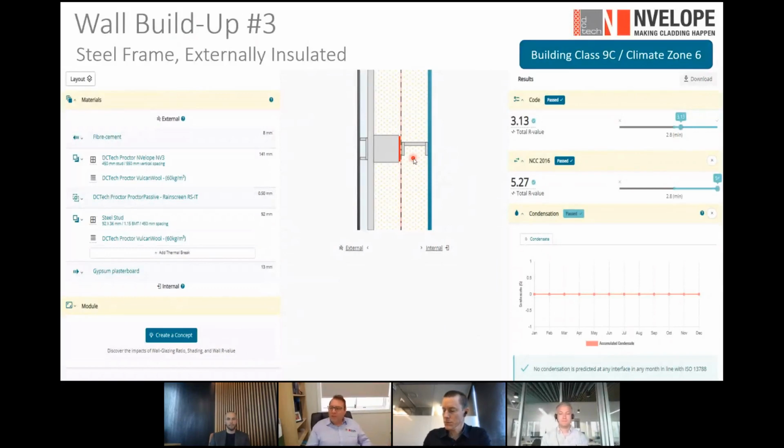But the big plus here is that we've moved the dew point. If you were internally insulating, your dew point would be expected behind the vapor permeable membrane. So that's where we rely on the permeability of that membrane to allow for drying potential outwards. When we have that dew point in those colder months, where the insulation might get wet, the permeability allows it to dry out.